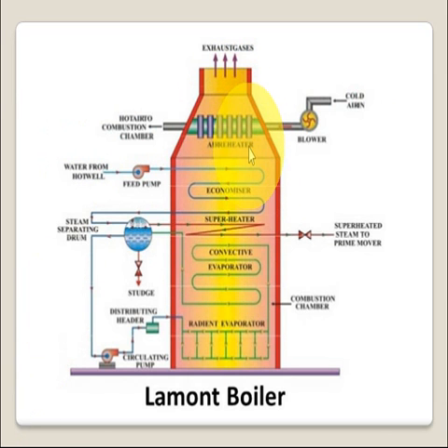This is typical picture of Lamont boiler in which this is air preheater and this is the blower for supplying air. Then we have feed pump, economizer, steam separating drum, then radiant evaporator, convective evaporator and superheater.